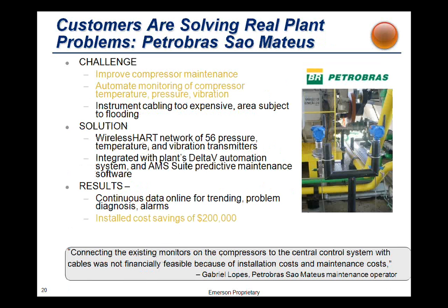Improvements in compressor maintenance. Things like vibration in the past. Today, fitting a simple vibration transmitter is a matter of just putting a simple clamp on a 2-inch pipe and a magnetic coupling, if it's only temporary, directly to the motor. Within 5 minutes, you have a measurement fully operational and ready to use. This was just not possible in the wired world.